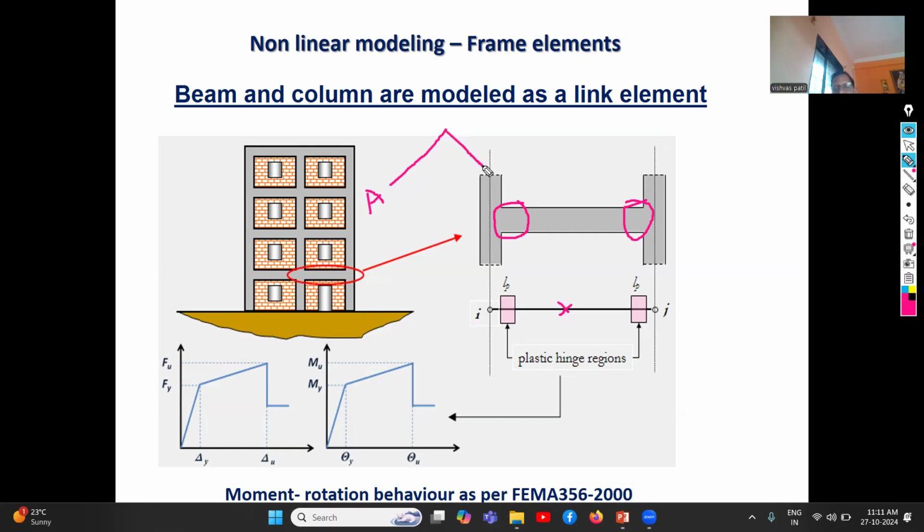Second, if an auto hinge for this particular element is not available, for example if the element is not a conventional type, then the user is required to calculate the properties of the hinge and then assign them.